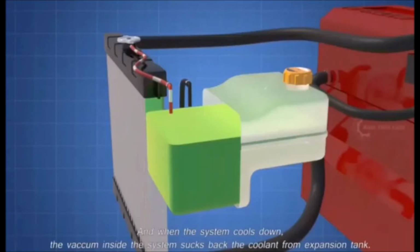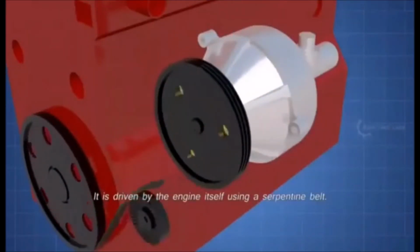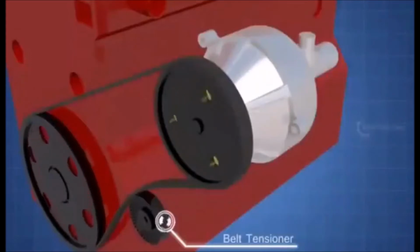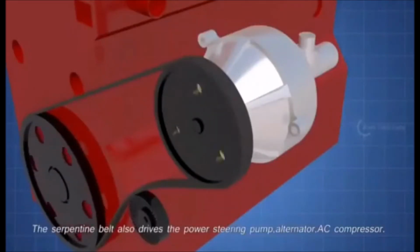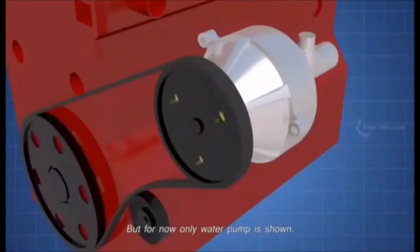And when the system cools down, the vacuum inside the system sucks the coolant back. The water pump impeller is driven by the engine itself, using a serpentine belt. The serpentine belt also drives the power steering pump, alternator, and AC compressor. But for now only the water pump is shown.